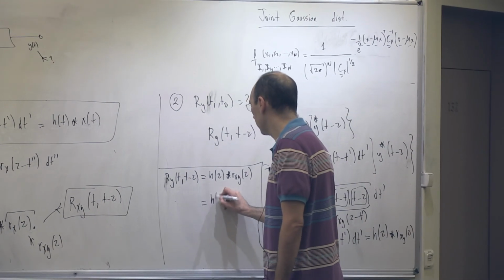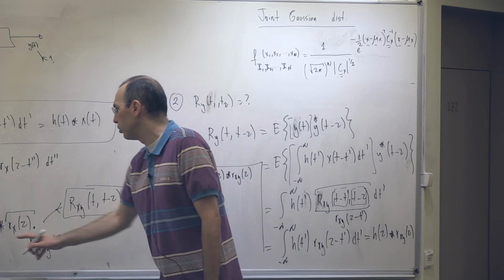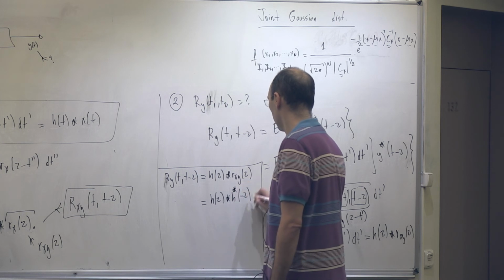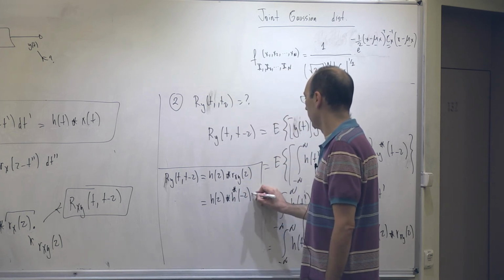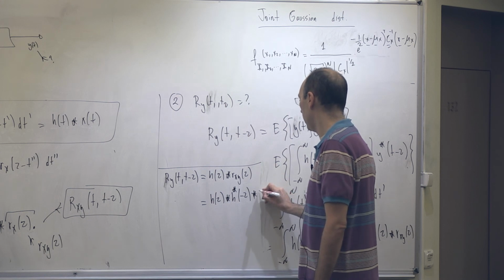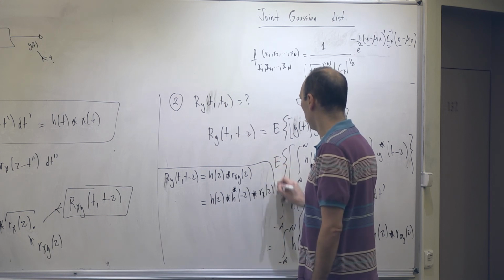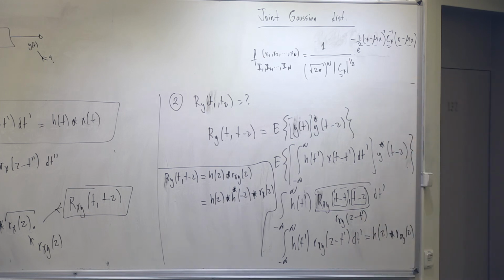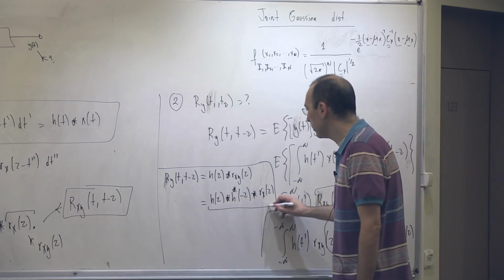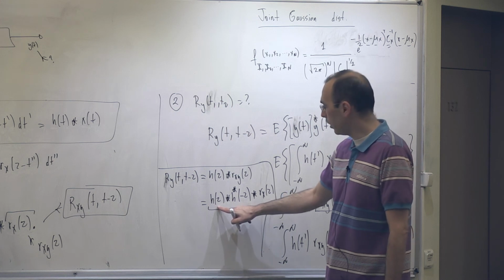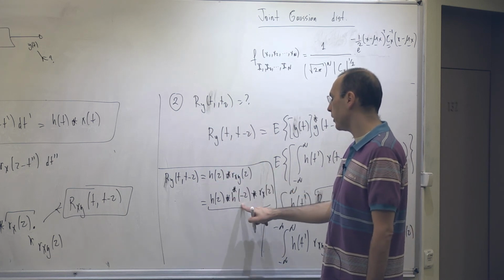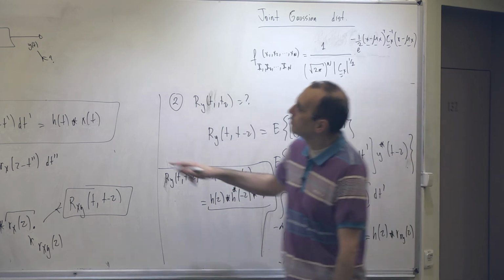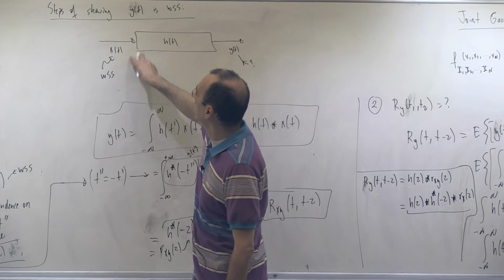As you see, I have two convolutions in cascade for this calculation. Clearly, at the end of this there is a one-dimensional signal in tau, another flipped version of it actually, another one-dimensional signal, and this is the autocorrelation function of this input process.